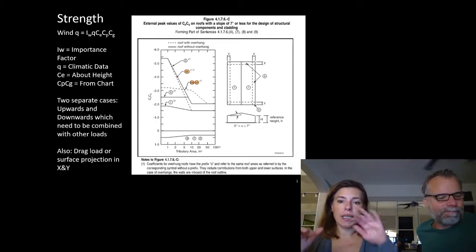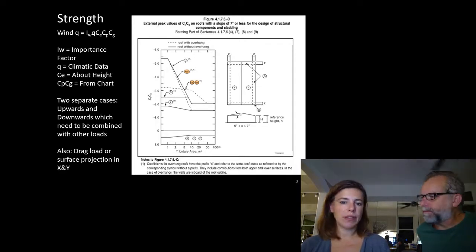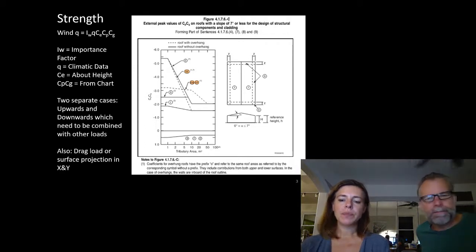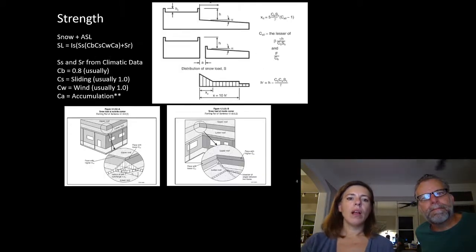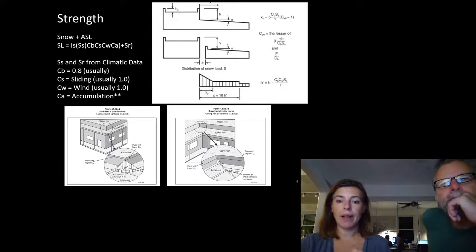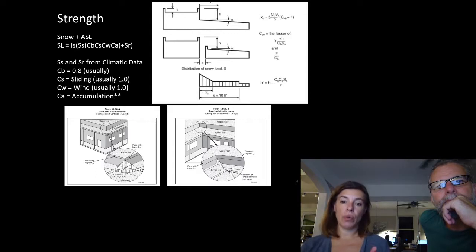For me, I'm often doing something that's got trellises or something like that, and so using 2% is totally reasonable for something like that. And it's just friction, right? Yeah, essentially, as the wind blows around it, along it, it's still gathering up some of the load. So this is why in Toronto, I don't mind being somewhat conservative with my wind load. For Dave, doing something like a canopy in Bermuda might be more refined about his wind load, because his wind load's going to govern. But for me, the majority of the time, the snow load is governing.